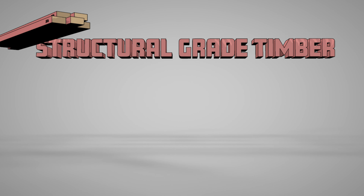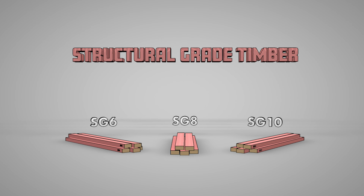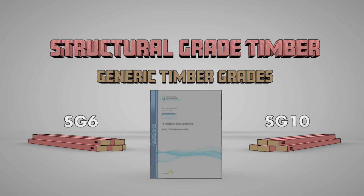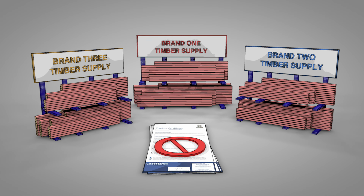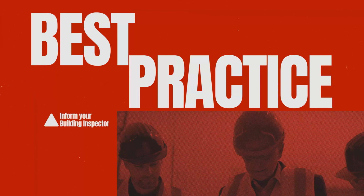To determine what a simple variation would be, let's have a look at a typical example on structural graded timber SG6, SG8 and SG10. These are generic grades written into the timber design standard. Most timber suppliers stock these grades, which are clearly identified on the product. Therefore, if one of these grades specified on the plans needs to be changed from one timber supplier's branded stock to another supplier's brand, then no supporting documentation is required because they all carry the same generic timber properties across the board. However, it is best practice to make the building inspector aware of this change.